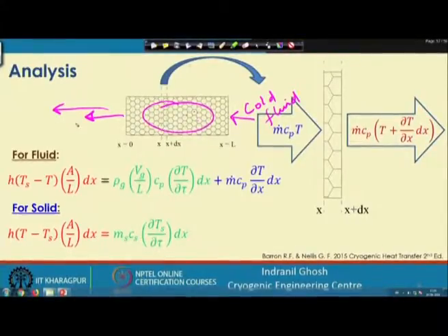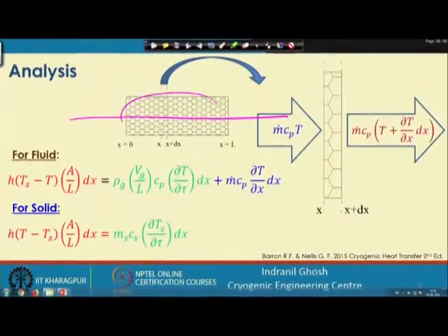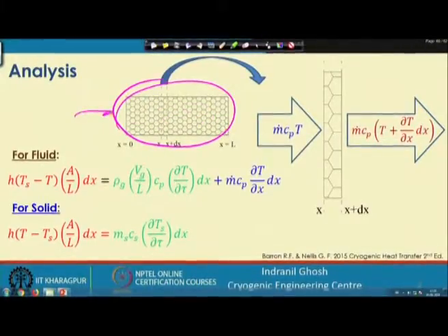So, the same fluid goes in one cycle, leaving its heat over here, and in the next cycle it moves in the opposite direction, picking up that heat. That is how this storage type of heat exchanger works. It allows the fluid to store its energy here, and then in the other cycle it picks up the heat it has left in the earlier cycle.